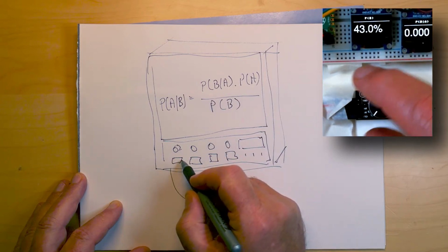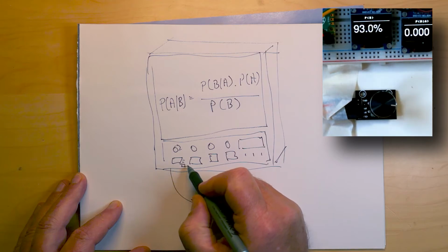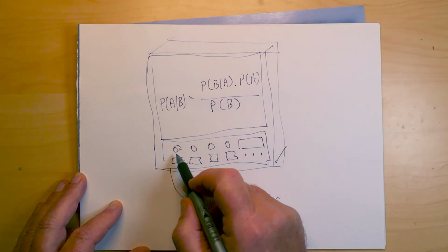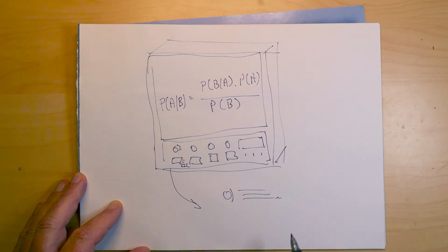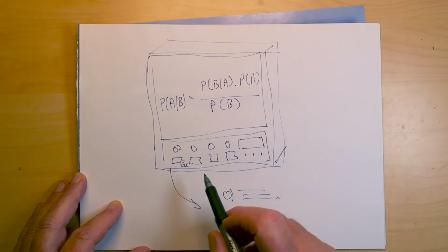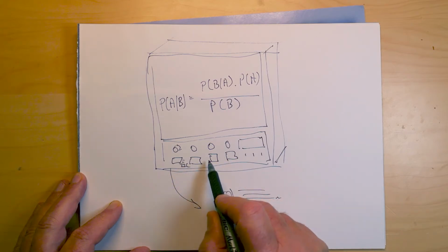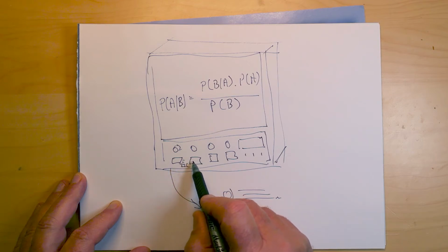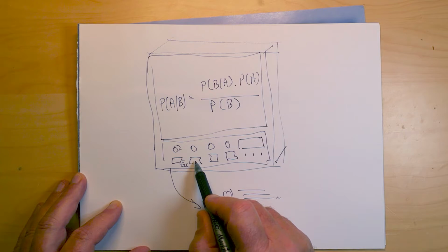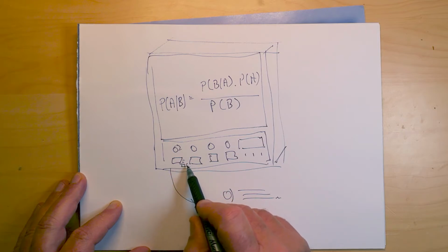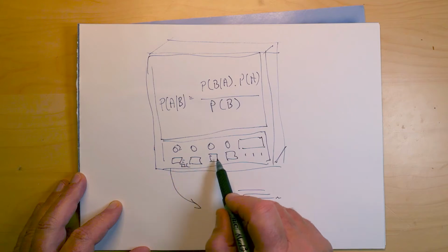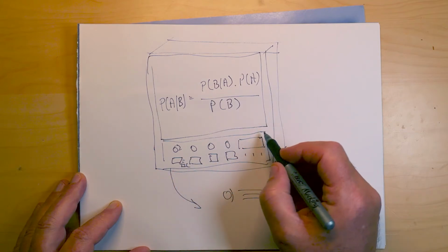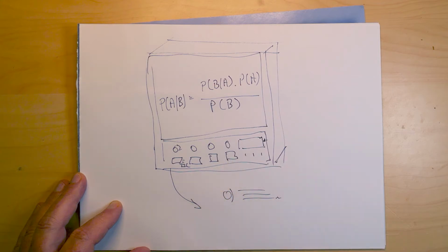And these displays here will be I2C, so I need to have these work in coordination with the knobs. This will all be running on a Raspberry Pi Pico microcontroller because it's got lots of I/O on it. It's got a couple of I2C buses, so I'll be using the I2C buses to run these. Each of the displays I have can have one of two values for the addresses. So with two buses, two addresses on each, I can control 4 of these, and then this third larger display will have a separate address, so I can run that on one of the buses as well. So that should all work.